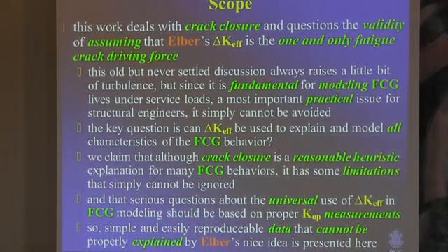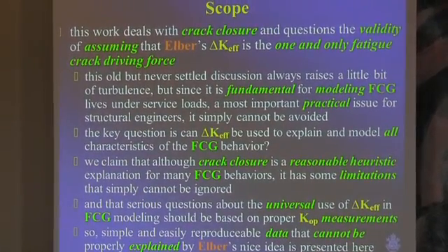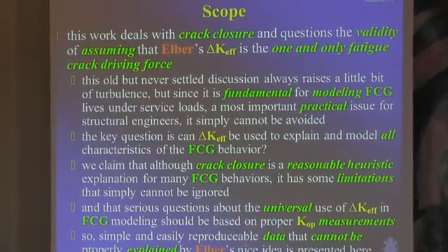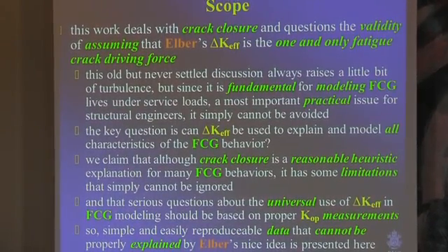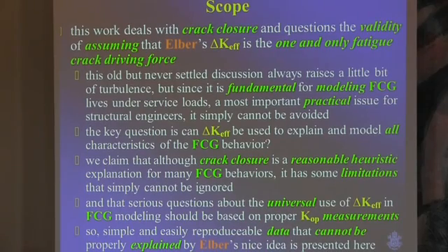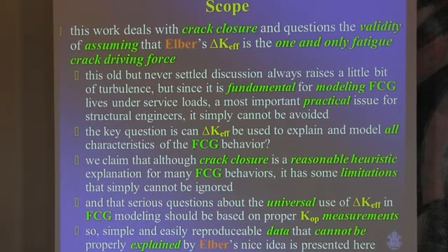to look carefully at crack closure, and particularly the validity of assuming Elber's idea that the fatigue crack driving force is delta K effective. That for me is a very important point. It's a very old discussion, never settled, because we still are using this idea in mechanical design.